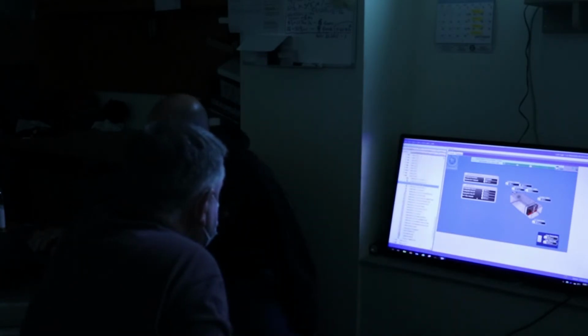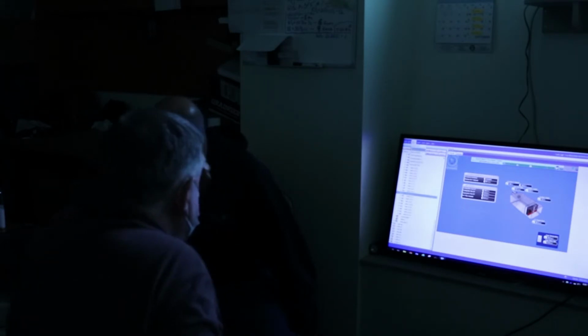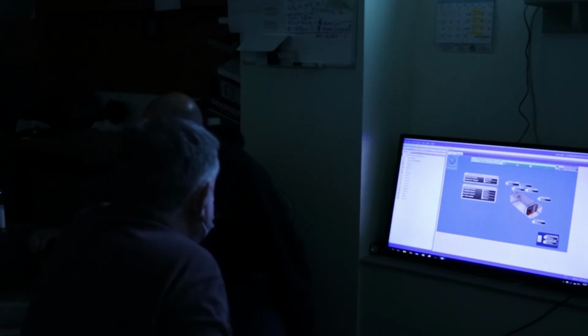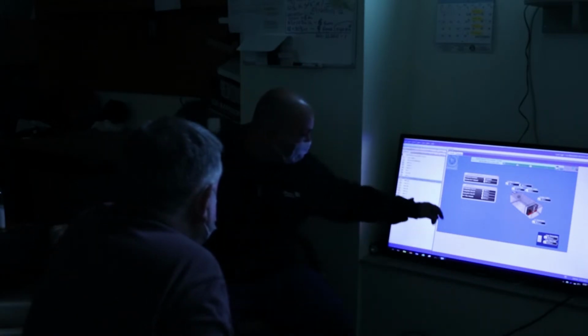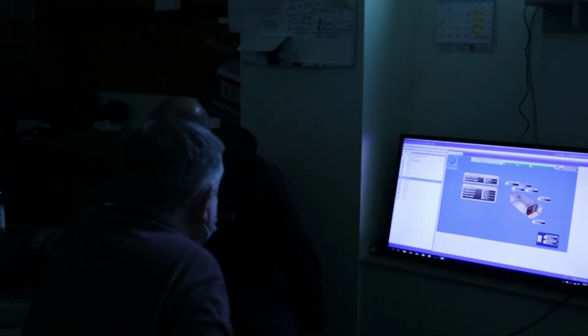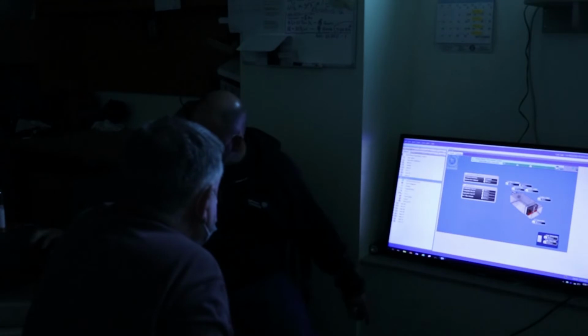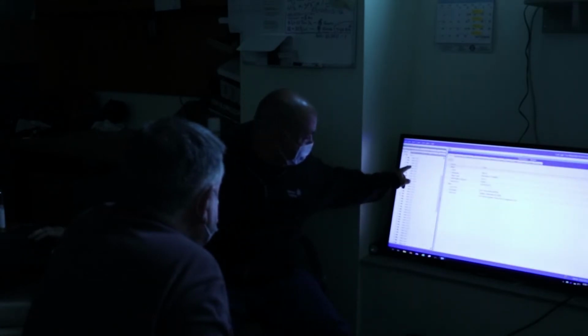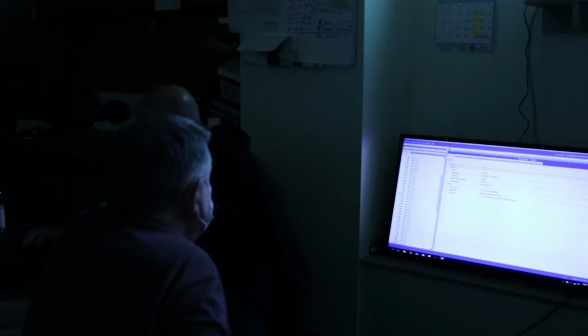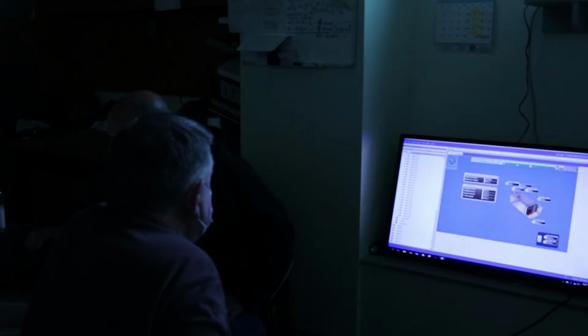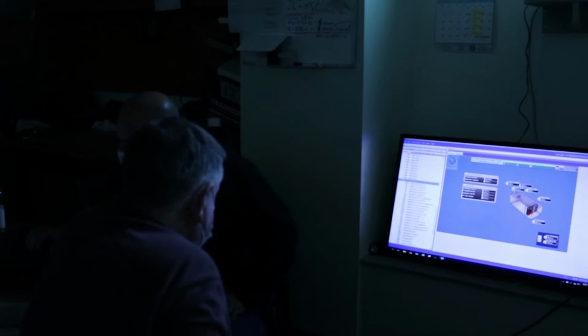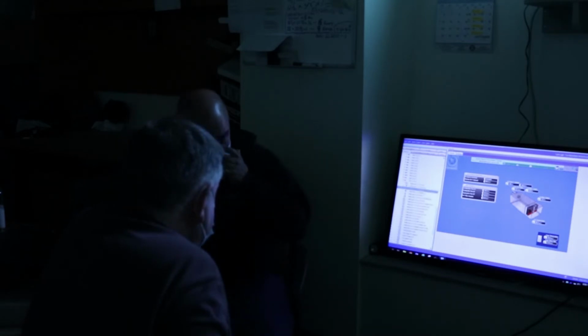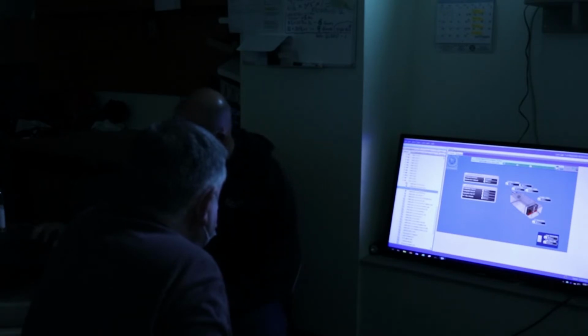So we come over to the tree, and when you first get there, it's going to look like this. So we go to NAE5, see NAE5? Now we expand it. FC2, you see FC2? And now we look for the VAV we want. So it was 1510. Now we open it again, and now we see the zone temperature. There's the point. Okay?